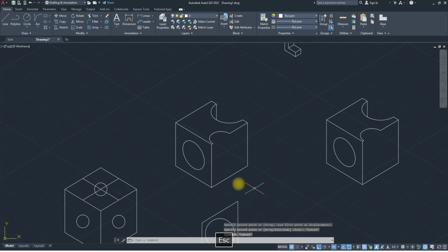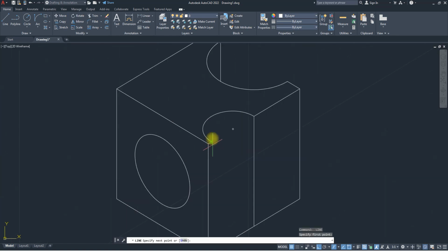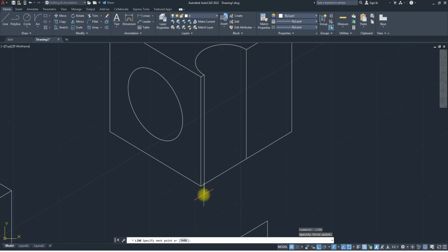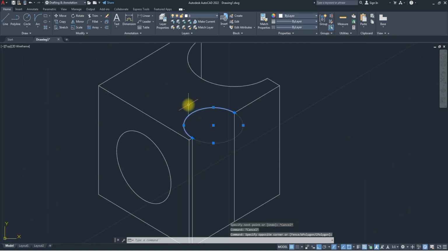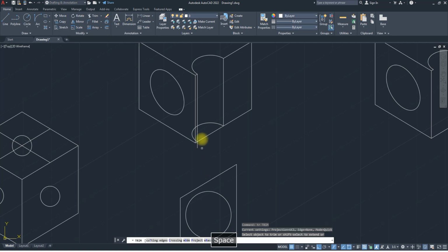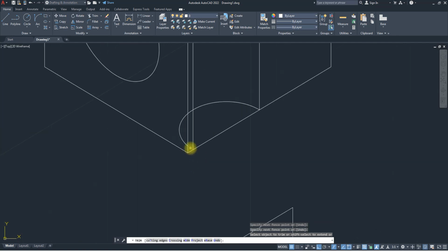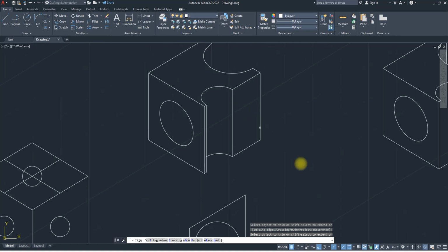So here we're going to do, let's assume we're chiseling this thing down. So what we're going to do is create a line, switch our view to bring this all the way down to this place, and also from here, all the way down to this place. But that's not all. We still have to bring this guy down. So that means we select this, we have to use our copy to move from here. Click here, go to the next place, click to paste it before we can now start trimming. So we know we are going to trim off this, this will go, this will go, this goes, this also will go. And then we have that.